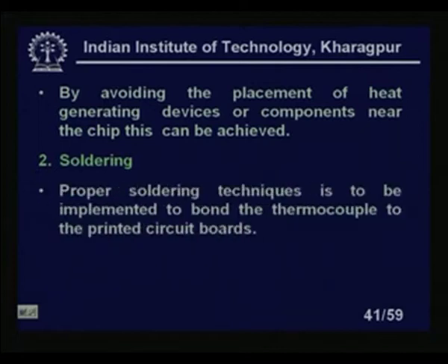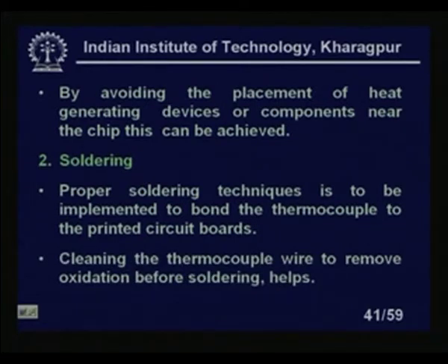Soldering. The proper soldering technique is to be implemented to bond the thermocouple to the printed circuit boards. Proper, with typical flux, that means there should not be dry soldering. Cleaning the thermocouple wire to remove the oxidation before soldering helps, because some thermocouples like iron constantan are very prone to oxidation.